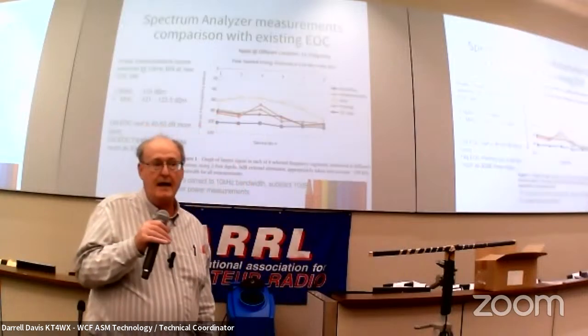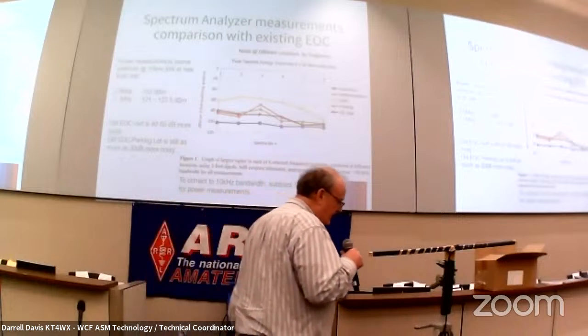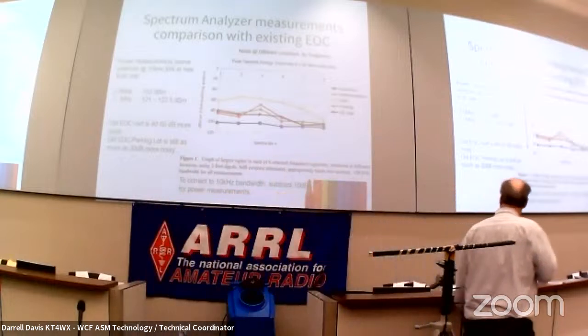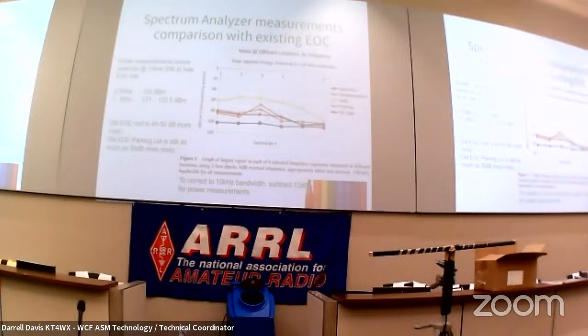I want to show you how this compares to what we did at the old facility. Now, I didn't have antenna factor back when I did that. What I had was just dBm, but it was the same exact antenna. And this is stuffing that antenna through the trap door onto the roof of our EOC, where our big fancy antenna was hung above the roof. Now remember I showed you the measurements before, which was like negative 122 dBm. Well, this was negative 60 dBm.